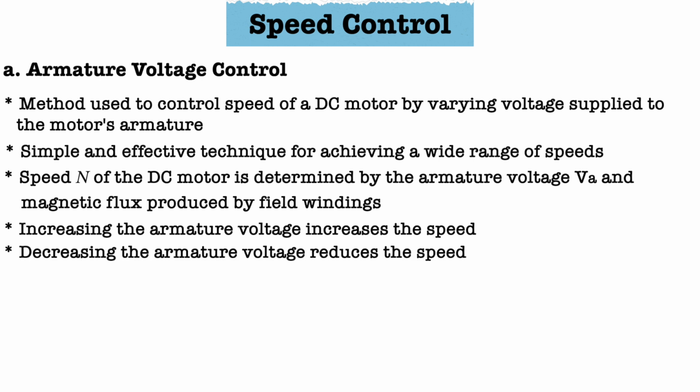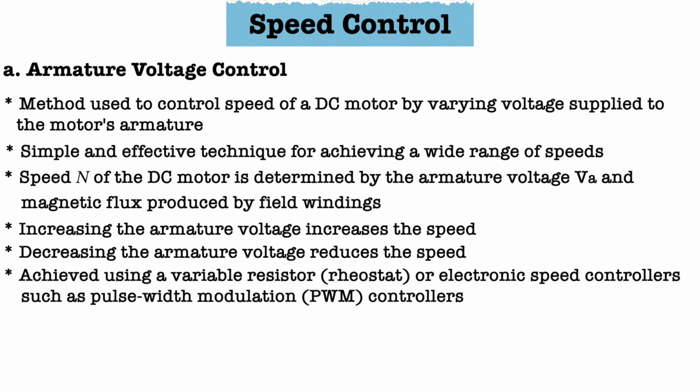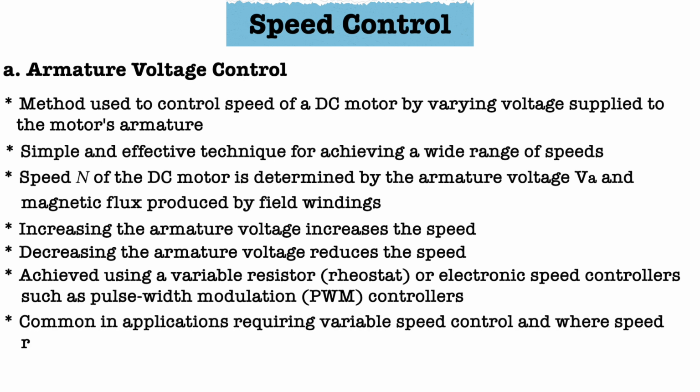This method can be achieved by using a variable resistor, rheostat, or electronic speed controllers such as pulse width modulation controllers. And this method is common in applications requiring variable speed control and where speed regulation is a must.